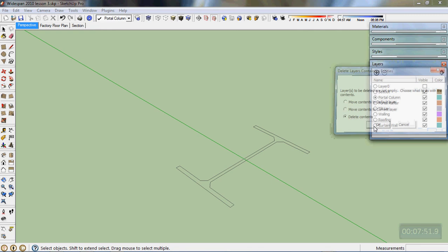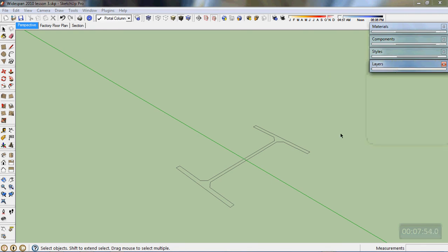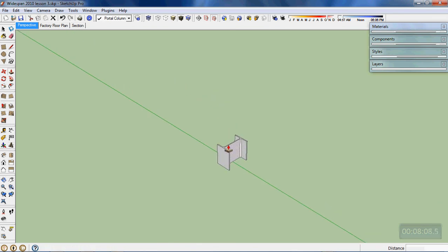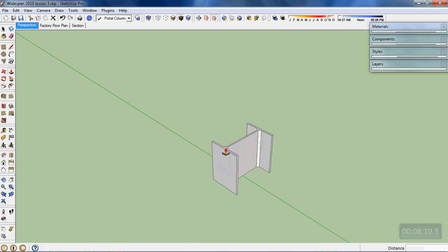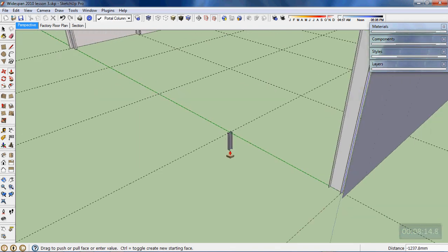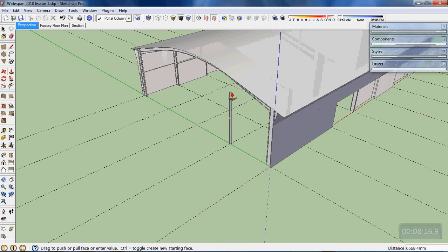So now that I've created this shape, I'll just trace over the top of one of the lines, turn it into a face, and then we'll start push-pulling. So I then want you to push-pull each of those. You might have to do it in a few stages, and if you're clever, while you're holding push-pull down, you can actually use your scroll wheel to zoom at the same time. But I'll just push-pull that one to show you in that location.